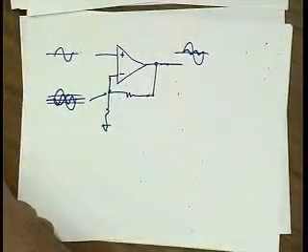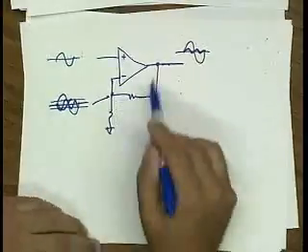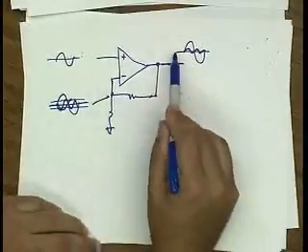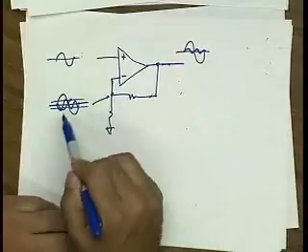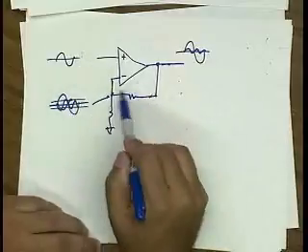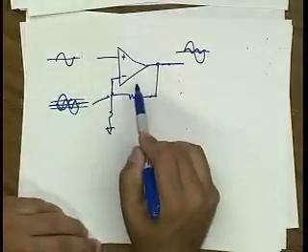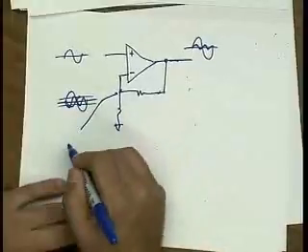It's trying to cancel the distortion in the op-amp. Exactly. It's going to introduce the opposite distortion. Very good. So what's happening is the op-amp internally is generating just the right amount of distortion to cancel the distortion that would be introduced by the amplifier. So it's pre-distorting the input.